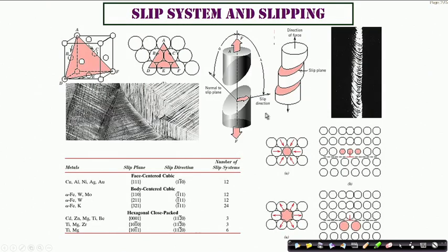And these dislocations, either edge or screw, are very, very important because they account for the deformation or shape change of all crystalline solids, particularly metallic crystals, because deformation using such line defects is energetically always more favorable. It requires a lesser amount of shear stress compared to a situation where the crystal is all perfect. So the defects have a role to play not only in defining the stability but also in defining certain characteristics or deformation behavior, or in general bulk or surface properties of the crystal.